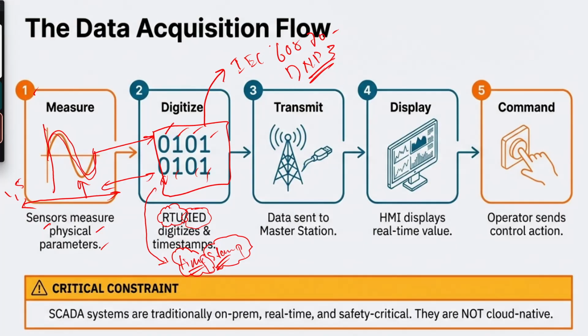What these protocols will do is encapsulate this digital data which is produced from these analog signals, right? And this is also where we are securely transmitting the digital data to our processing units, right? So now we are encapsulated, and by using some cables or else RF or else 5G or LTE, we are transmitting that encapsulated data to the SCADA system.